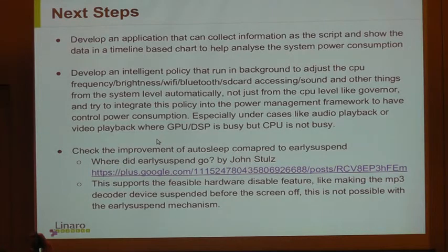And the third one is to check the impact of the auto sleep compared to the early suspend. And this is described by John Stout before. With the auto sleep feature, we can make the MP3 decoder device suspended before the screen off, which is not possible with the early suspend mechanism.